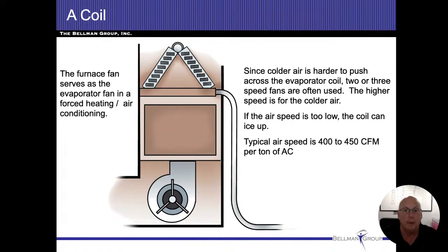But because colder air is harder to push through the ductwork, we're going to want to increase the airflow when we're running the air conditioning system. So as you're checking your airflow, and this is a lot of problems you're going to run into, even with new construction homes, people end up undersizing ductwork. It may be correct in the math, but it just doesn't work.